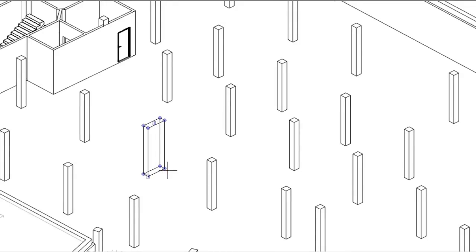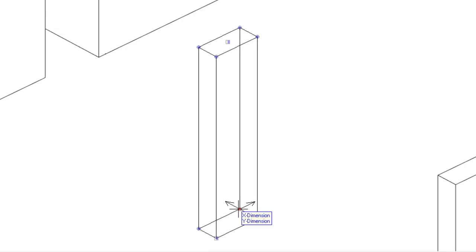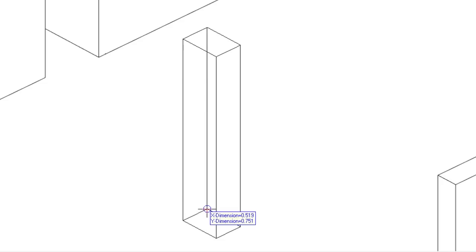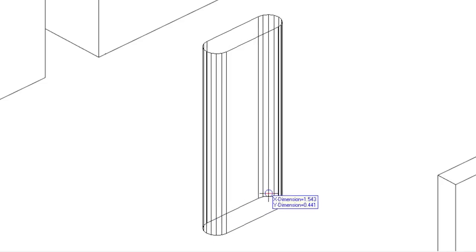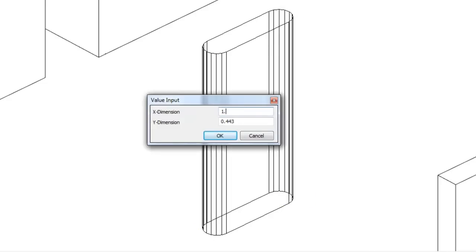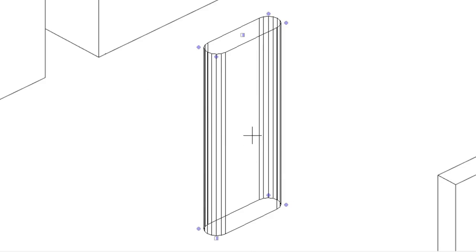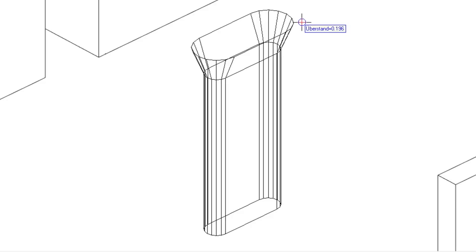As well as being able to freely specify dimensions by moving the handles, it's also possible to enter values directly. And if provision has been made for this, you can activate additional elements by means of clickable handles. Our SmartPart pillar is now extended by a pillar head with a haunch, and its dimensions matched to the project. Once the change has been completed to your satisfaction, all identical components automatically adapt accordingly. Previously, a number of additional steps would have been necessary to achieve this.